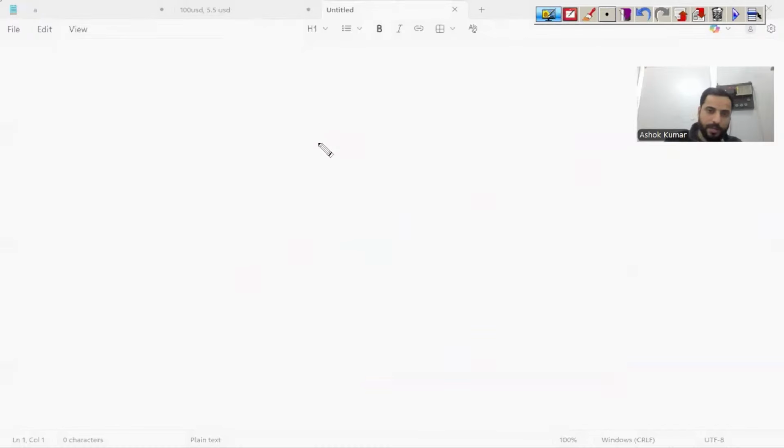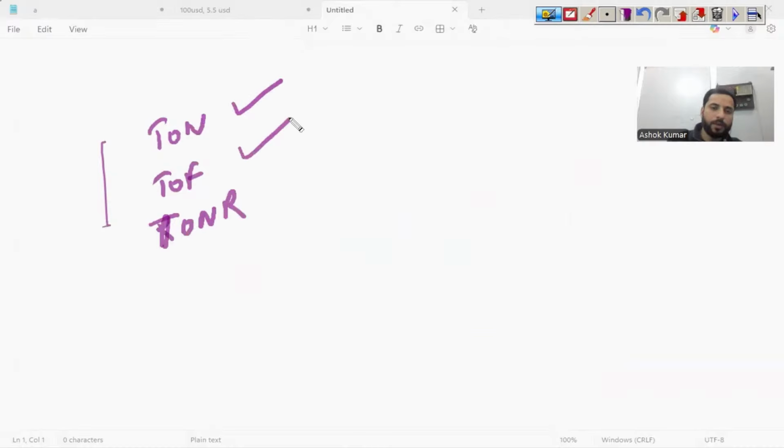clear this. So timers, basically here you have three timers, TON, TOF, and TONR. TON is on-time delay, TOF off-time delay, TONR retentive timer, same like Allen-Bradley.